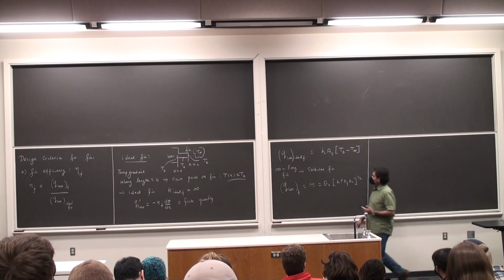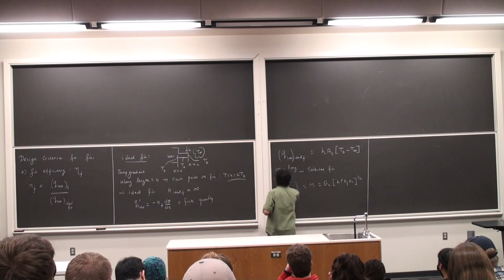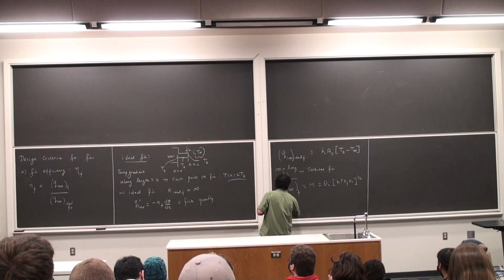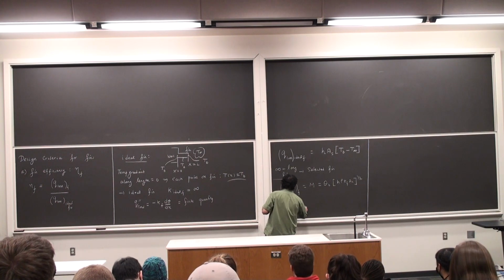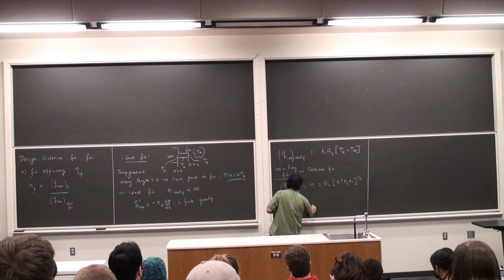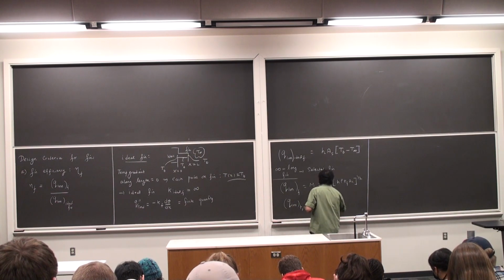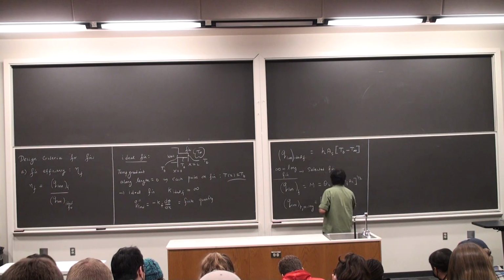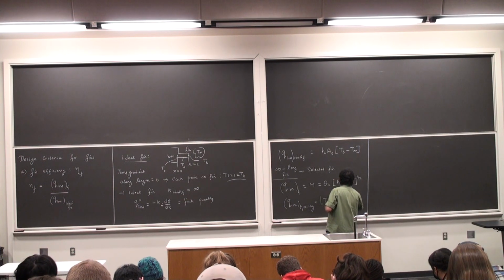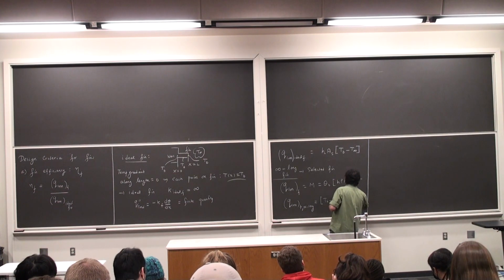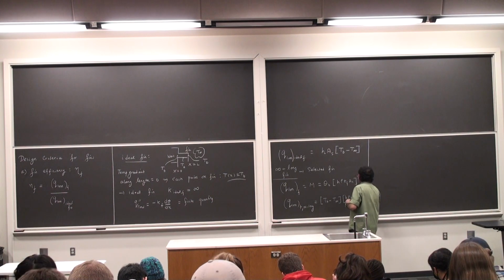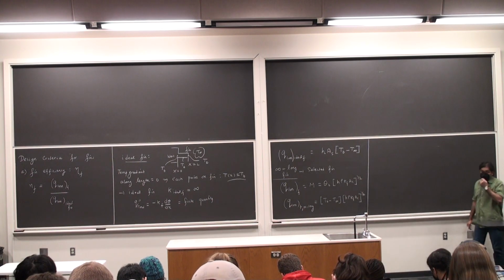So if I expand this out, Q loss for the fin, infinitely long, is Tb minus T infinity, h P Kf Ac to the power 1 by 2.